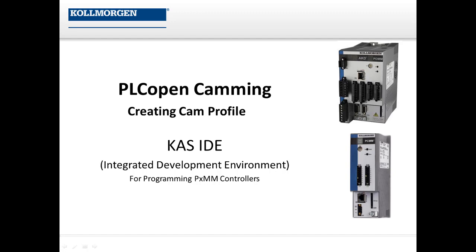This is the first video in a series that will show you how to implement camming into a PLC Open project with the KAS IDE software. Before we go ahead and add function blocks into our PLC code, we have to create a cam profile. We're going to show you how to use the tool inside the KAS IDE to either import or create new